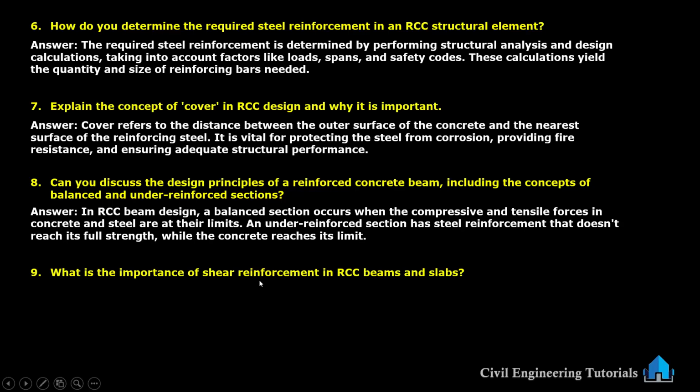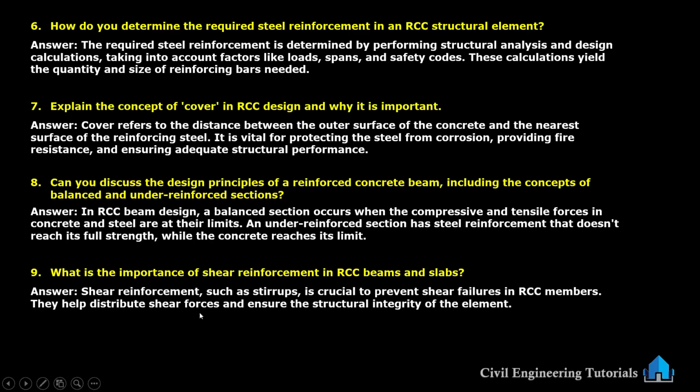What is the importance of shear reinforcement in RCC beams and slabs? Shear reinforcement, such as stirrups, is crucial to prevent shear failures in RCC members. They help distribute shear forces and ensure the structural integrity of the element.